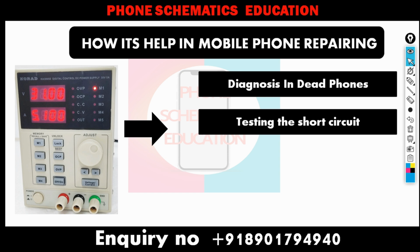When you connect your DC to the motherboard and it takes auto consumption, auto current, I mean auto reading, without pressing the on off button, that means there is a short circuit. If the current consumption is high, then we call it a full short.